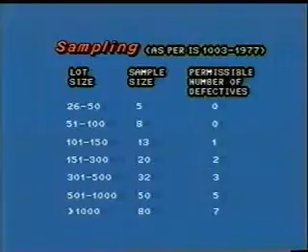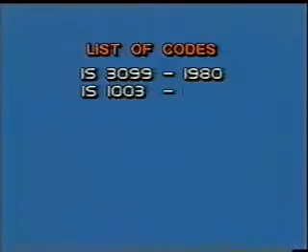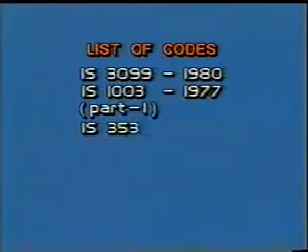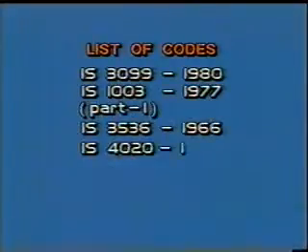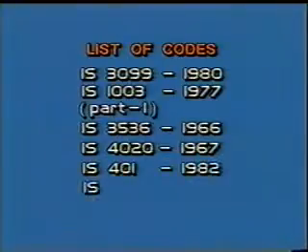If a shutter fails any test, then double the number should be subjected to the same test. The relevant codes of Indian standards for factory-made shutters are as shown.